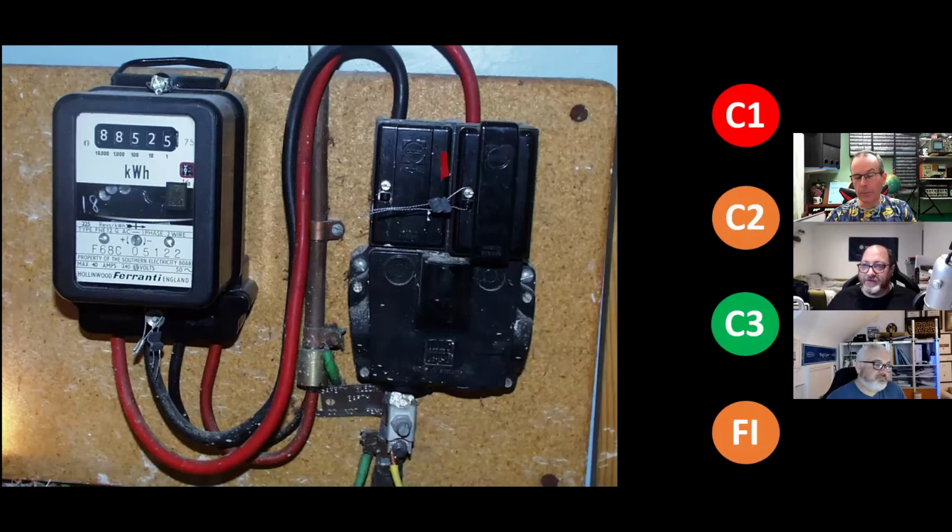And actually on that bottom bit, there are 2 clamps on the outer of the cable, because there's the one at the solid green, which is like a copper one underneath, and then you've got the 951, which has been put in partially over the top of that. There are 2 different types of clamp on that. And so, what's that other green and yellow doing? Is that a local bond? I can't remember. I don't think so, because all the services were upstairs, and the gas meter was upstairs as well.